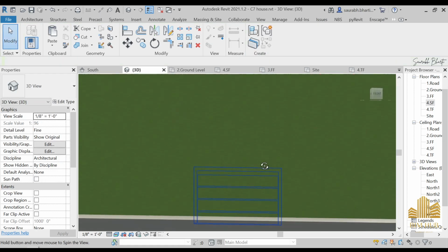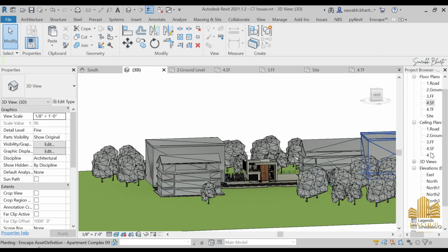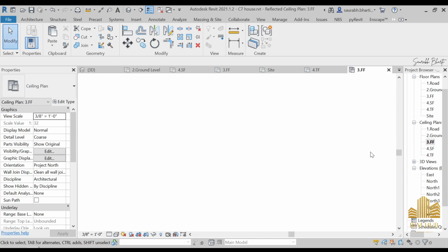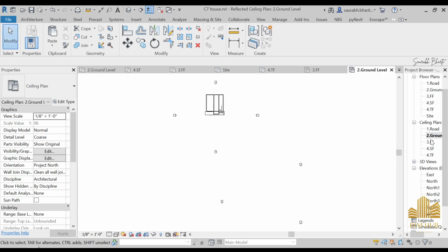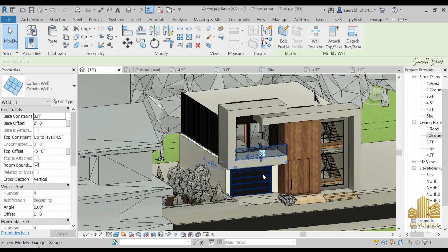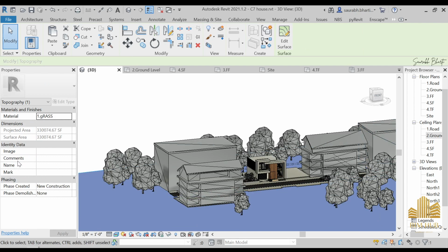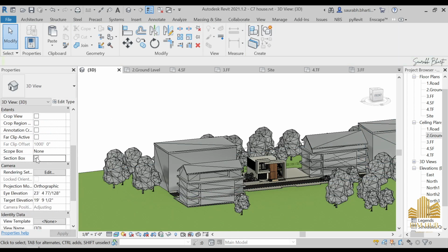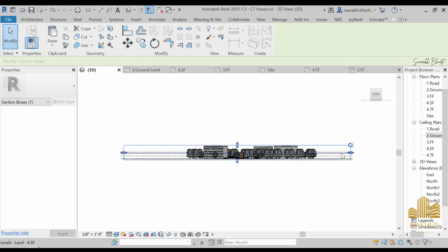Okay, and then we have to put some of the ceiling family over here. So just go to the first floor or the ground floor. Okay, we had not made any ceilings, and we have to put something over here. So for that, you can go to the section view, activate this section view, make it a little bit smaller, and first of all hide all the components.